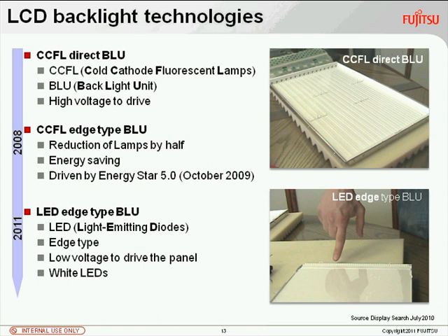These are the tubes that make the light. You need a lot of them because otherwise you don't see a homogeneous brightness, but only bright stripes and dark stripes on the display. And you need quite a huge distance, which is the thickness here, to spread the light over the whole screen. So the old screens were quite thick, quite heavy, and with a lot of lamps, they used a lot of energy.